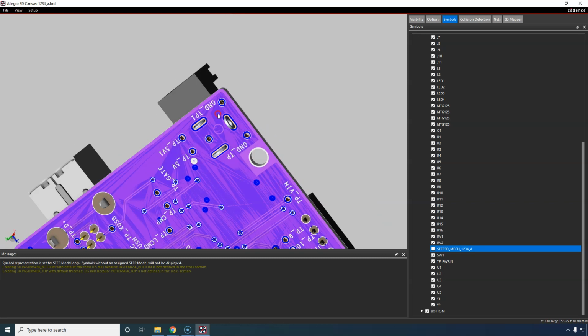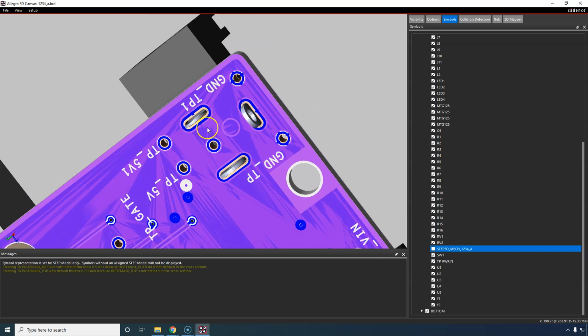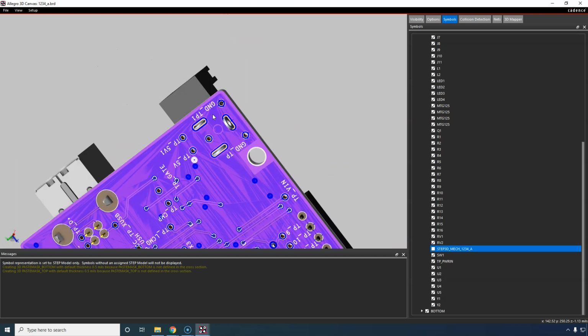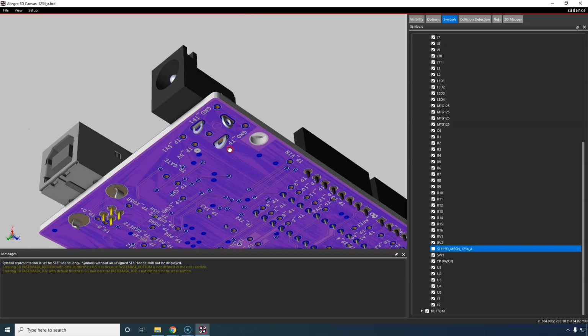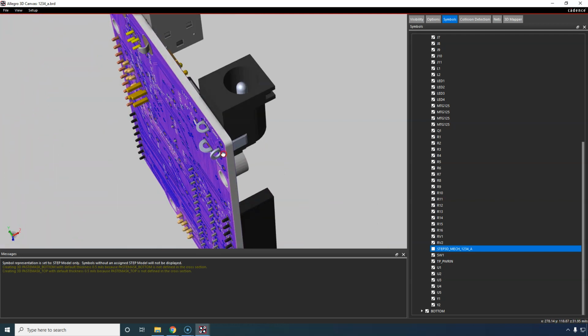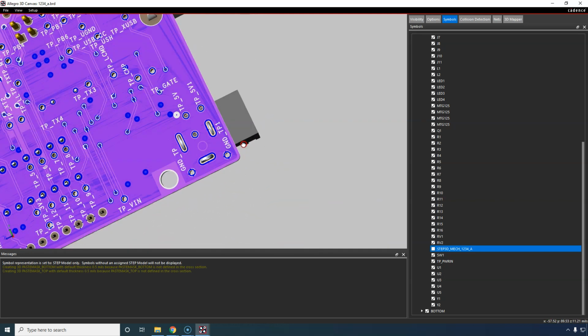I used to make PCBs on a CNC milling machine. If I had a drill bit and tried to do this, it would break immediately. If I drilled down here and told the machine to move this way, or if I put the wrong bit in the routing instruction, it would break the drill bit immediately. And the drill bits are expensive. Let me tell you, I'm talking about $25 to $125 per drill bit. So what do we use to drill this out?